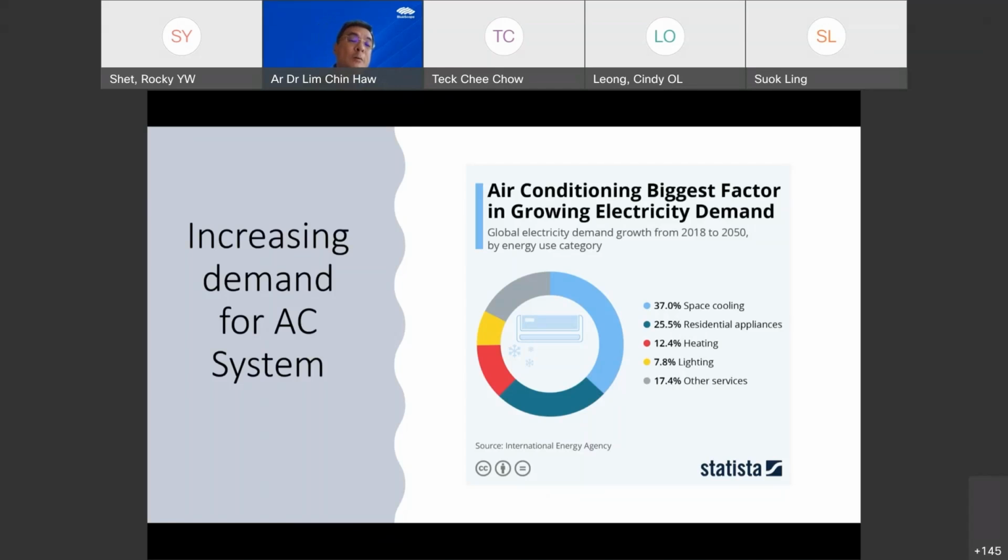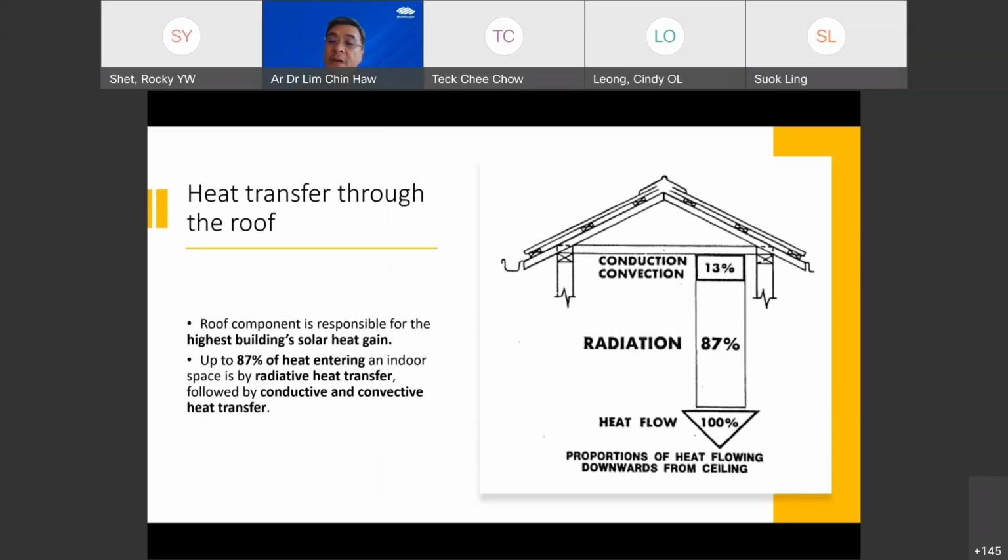All right. So in terms of roofing, it's very important to look into the roof because, compared to other building envelope systems like wall and glazing and so forth, the roof is one of the major ones. Why? Because we are located at the equator, so the sun is always on top of us. So the radiation or heat transfer comes from the top, which is the roof, especially for low and medium rise buildings. Not high rise, of course; for high rise, the facade is the major component where you take in a lot of heat transfer, right?